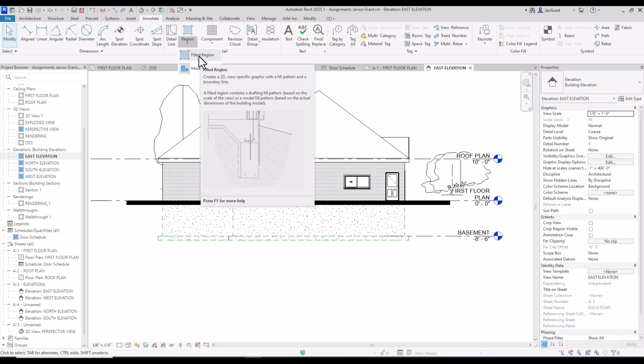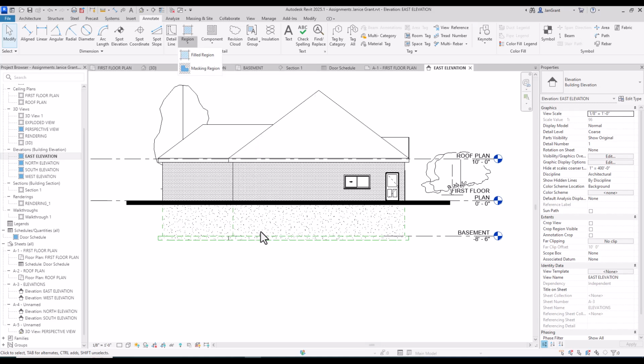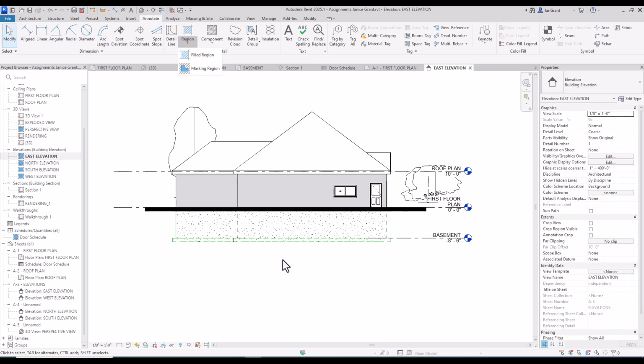This is where you're starting to get very detailed and bringing in your anchor bolts and your 2x4s and all of the materials that are components that you would load and then create that detail. So I just wanted to show you this is like the hatch and also that you could change your line weights. And so this is kind of one way to create a nice way to show your elevations.